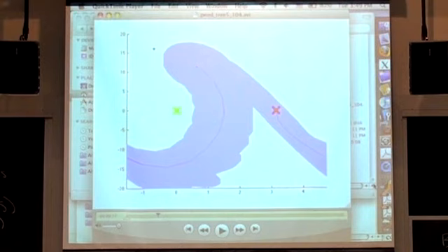Okay? So I get another random point, which is here. I'm going to pick the closest point in my current tree, which was just in this case a trajectory. Connect that back. Now this one, my dynamic distance metric, that LQR distance metric, said this was the closest point. Looks a little surprising, but maybe the torque limit said that one couldn't get there, or maybe my distance metric just wasn't perfect. But that's reasonable. It tries to go from here, add a little bit more torque, and drive out, and I stabilize that with a funnel.